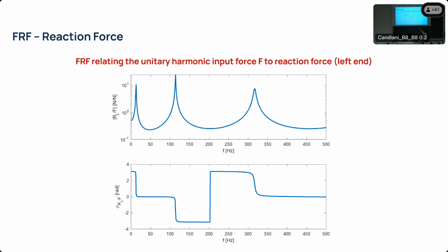If we go through some of the vibration modes, that force will amplify a lot. If we go through some of the other vibration modes, that force will decrease a lot, because at some frequencies the structure in a way is absorbing all the external forces, is damping out the external excitation. At some other frequency, it's amplifying a lot. So you have to take that into account when you design a structure or a bridge or whatever you are trying to design.